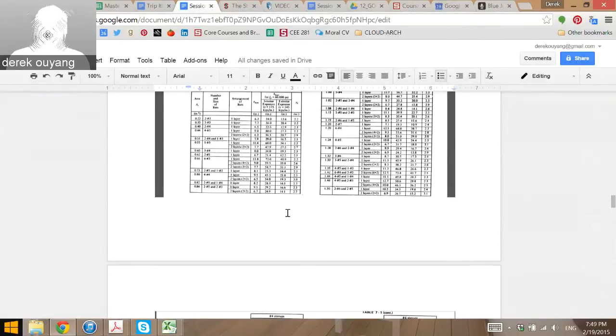And then all you have to do is iterate on this. Right? That's your only design problem, is just find a good aspect ratio here. And even that you probably can just guess, because you can usually just say that B is probably going to be half of D. And D is usually going to have a 3-inch cover below the rebar, so H is going to be D plus 3. So you can actually build that into here, and then here you can make a quadratic equation.